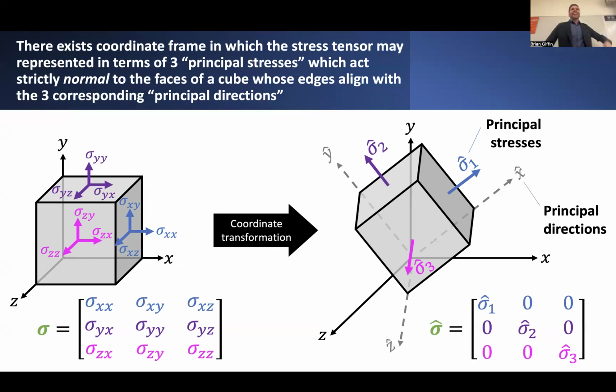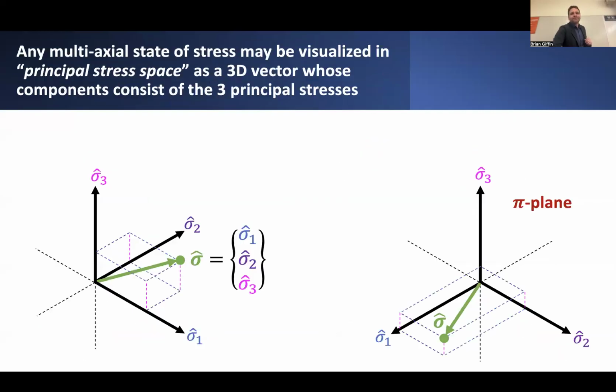And obviously, analyzing principal stresses has general utility if you want to know what's the maximum principal stress or the maximum tensile stress on any possible oriented plane in some chunk of material. That's useful for analysis and design purposes, but it's also useful for visualization purposes of states of stress as expressed through these principal stresses.